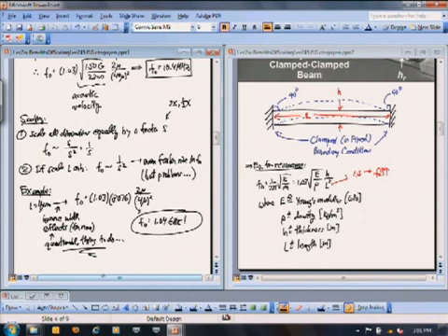So just so no one is confused by that, it really is going to end up being maybe 800 megahertz or something like that. Right? Those effects will knock that frequency down, such that in order to get to gigahertz, you would really have to make that length even smaller, but still a reasonable length. Okay? And so at least in this case, things look good.